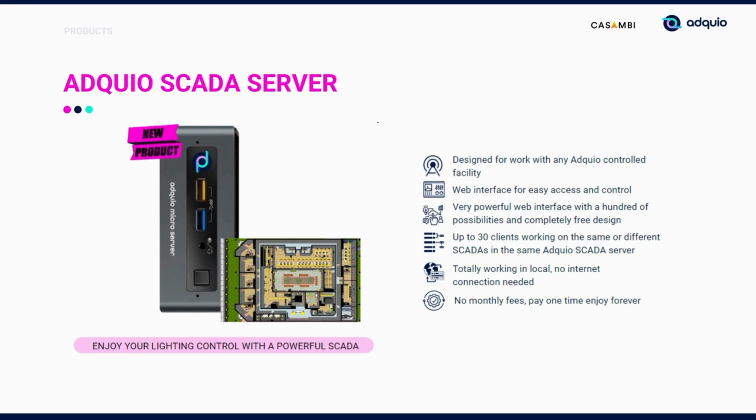It uses a web interface to display SCADAs, therefore you will only need a web browser to be able to enjoy all the content of these SCADAs. You will see that you can design any type of object: circles, squares, or any other type of figure. You can upload your own objects too. Above all, you can make these objects dynamic by connecting them to the variables of your devices. For example, you can change the color based on the content of a variable.